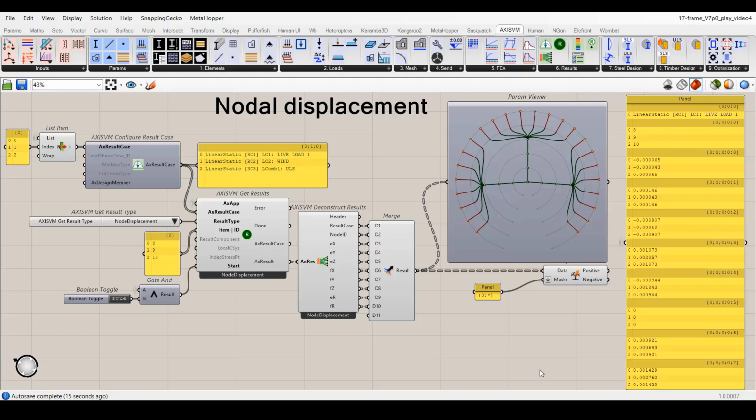For example, the displacement in X direction is stored in a list for node number 8, 9, 10 in this order. To make it more clear, you see the encircled region that contains the information about the result cases. The next level contains the node IDs, and the following 8 sub-branches contain the result components. Very similar data structure is used for the nodal support reaction forces.